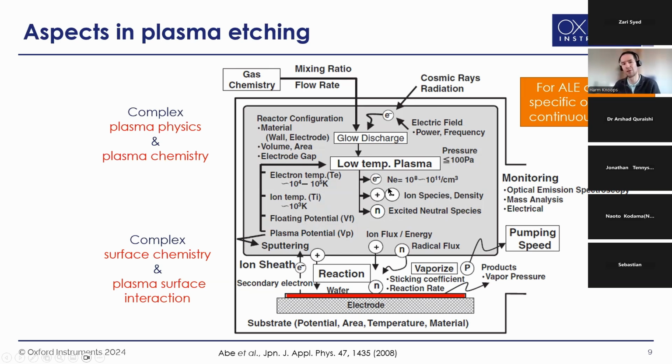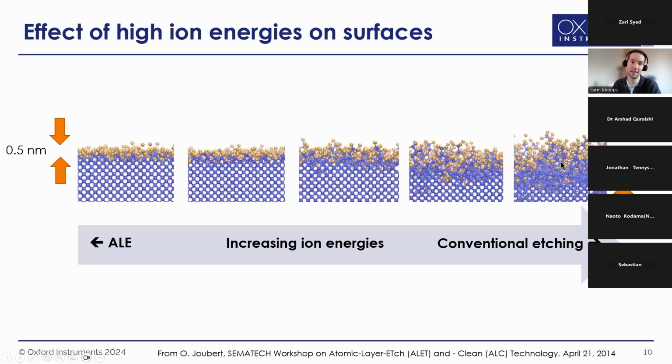And you can imagine for ALE, because it's stepwise, it's even more complicated, because when you start a certain step, the plasma is a certain way, and by injecting species or species coming from the surface, it's not steady state, so it can constantly change. That's an added complexity. Although actually that the steps are separated maybe also makes things simpler.